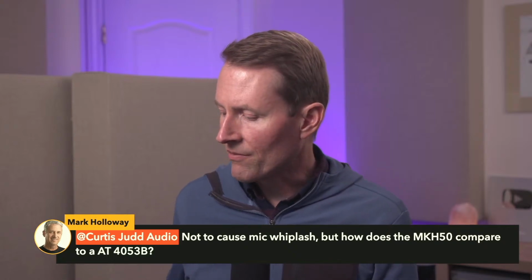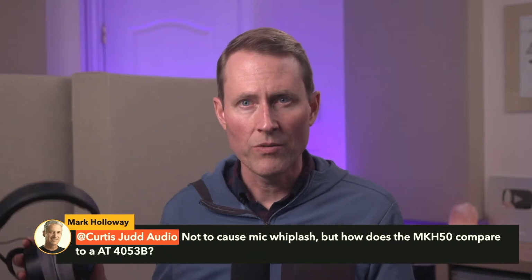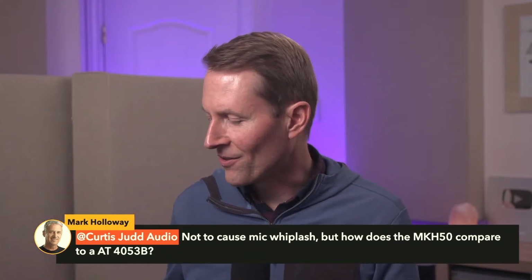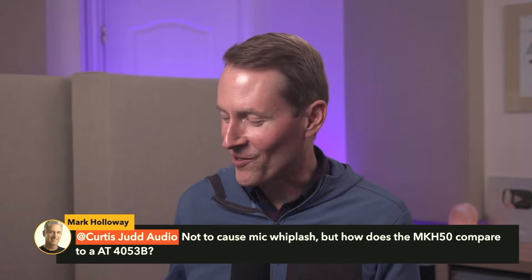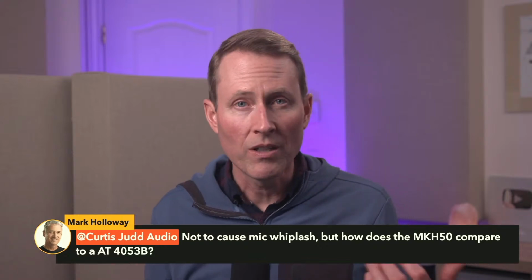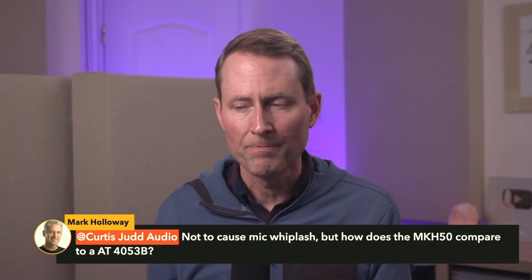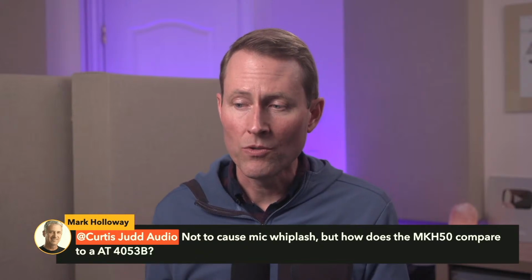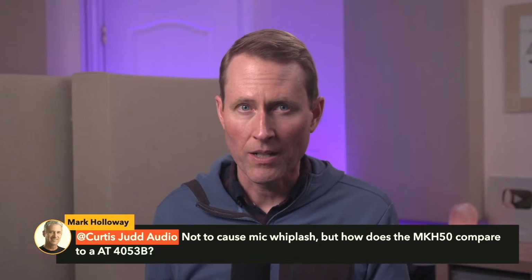You can drive high impedance headphones, and this is not a set of high impedance headphones, I was just holding them up to demonstrate, but high impedance headphones of 250 ohms with a MixPre without a problem. With a Zoom F-series recorder, probably not.